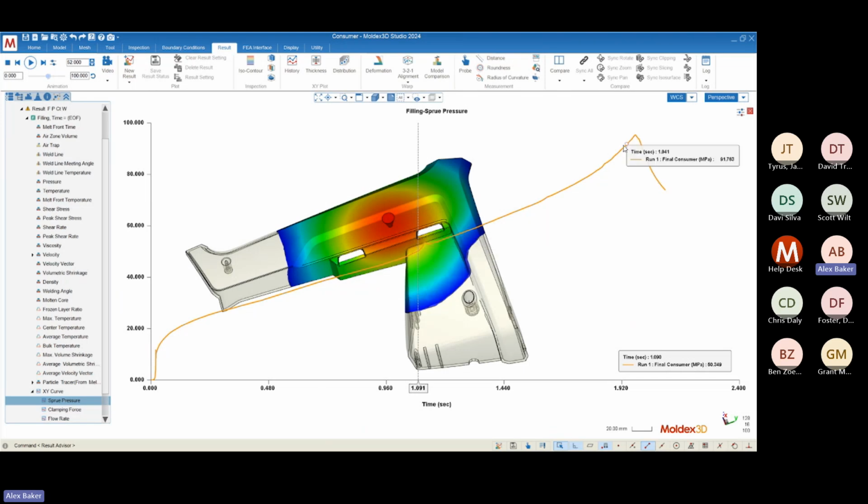However, if this pressure spike occurs closer to the end of fill or closer to this maximum pressure point, the amplitude will increase. And in most cases, that amplitude will increase above the expected maximum pressure, which first of all will create a very impulsive force onto the machine, which can hurt your machine long term. But second of all, it will increase the pressure requirement needed to make this part, which, if that impulsive pressure spike goes over or close to the machine maximum, is really where you can start doing damage, especially over a large number of cycles.